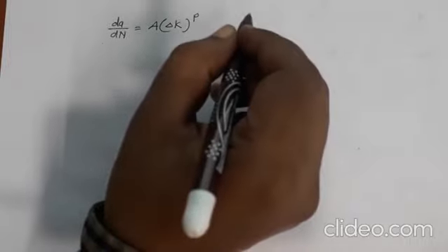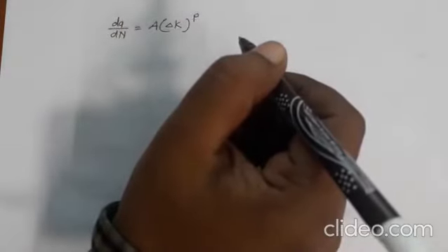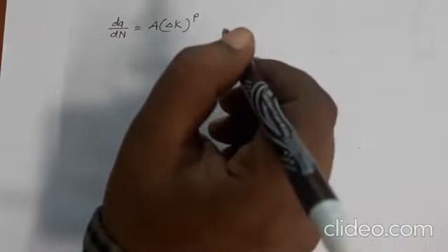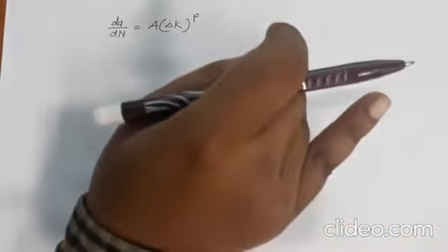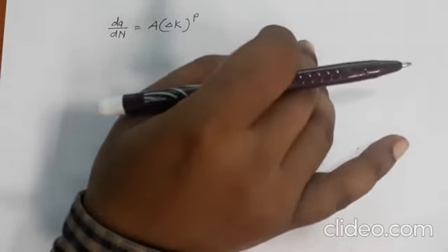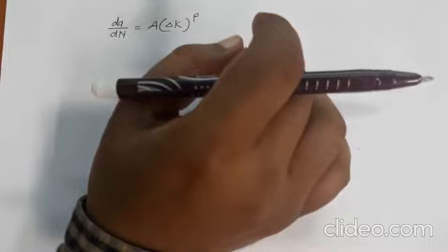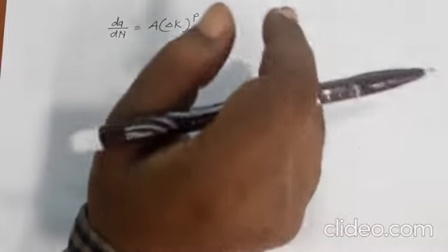So remember that when you do not have a crack initially, then we follow the SN diagram. When we have a crack, then we follow the dA by dN versus delta K plot. So that difference should be very clear in your mind, that there are two cases. One, we have no crack in the system, so we simply talk about fatigue. Once we have a crack in the system and we are applying cyclic loading, we are talking about fatigue crack growth. These two have different laws and different scenarios, because in one scenario we include the part of crack initiation, in the other we do not include that part because we already have a crack in the system.